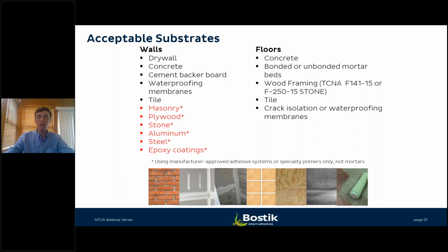But you'll find some applications that are suitable over drywall, some over concrete, cement backer boards, which are so prevalent throughout our industry, waterproofing membranes, as well as existing tile applications, with specialty adhesive systems, and in some cases, specialty primers, but generally not just a direct bond with mortars. You'll find applications over top of masonry, plywood, existing stones in some cases, aluminum, steel, or even epoxy coatings.